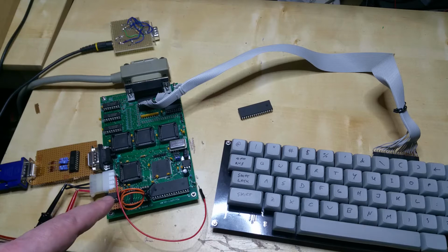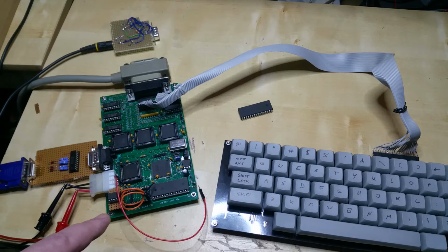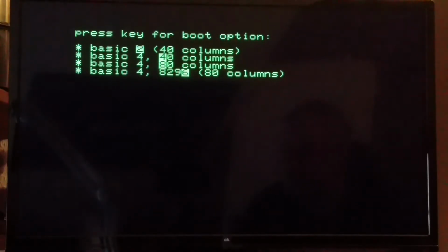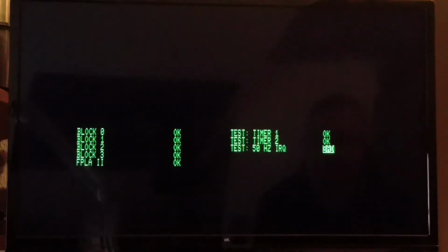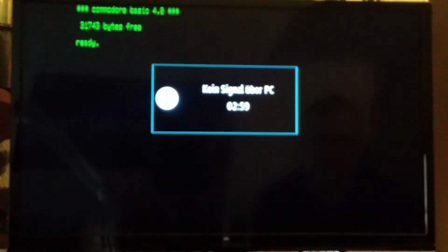By removing all the ROM related code from the CPLD, I was able to fit back in the VGA output and the 8296 emulation, and even add some more custom extra SPI channels. As you can see, the machine has a new boot option, 8296, which separates it from the normal 8032 machines. So I'm using this one right now to show you the capabilities of the emulation.